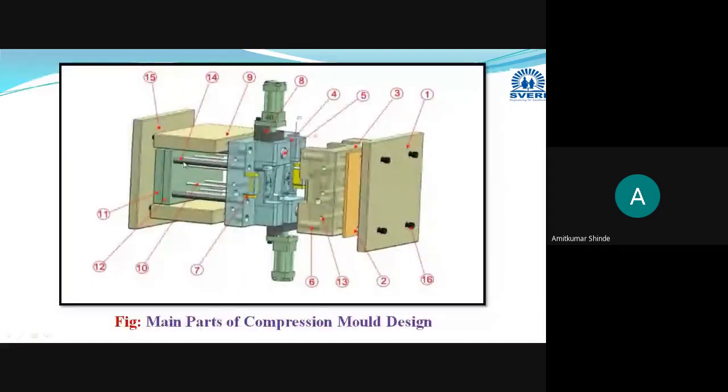Okay, this is the return pin 14. This is the return pin or pushback pin. Now this return pin will help you, after removal of the part with the help of the ejector pins, to bring the ejector pins to the initial stage or home position.